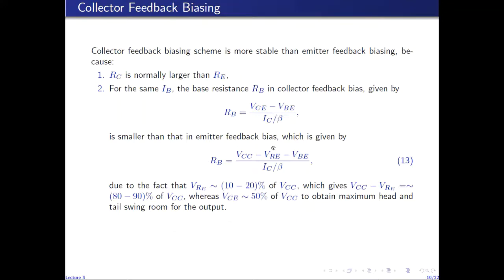Why? Because as mentioned earlier, VRE here is set to about 10 to 20% of VCC, which means that this term, VCC minus VRE, is about 80 to 90% of VCC.